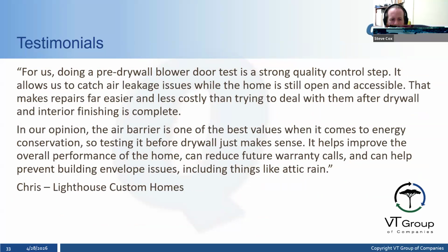Next, a slightly smaller home builder, Lighthouse Custom Homes. We do their blower door testing. Right now, we're just doing them at mid construction. So they do pre-drywall blower door tests as a quality control step. It allows us to catch air leakages while the home is still open and accessible. That makes repairs far easier and less costly than trying to deal with them after drywall and the interior finishing is complete.